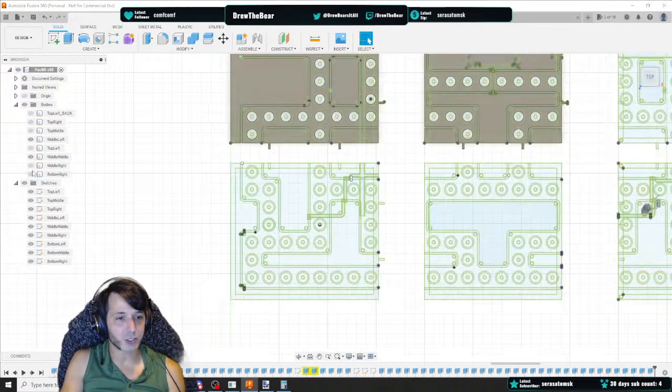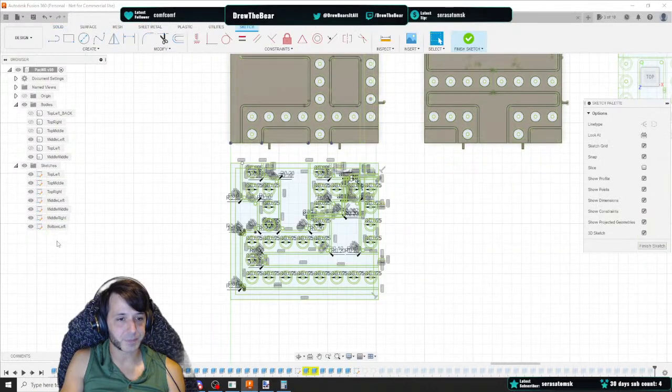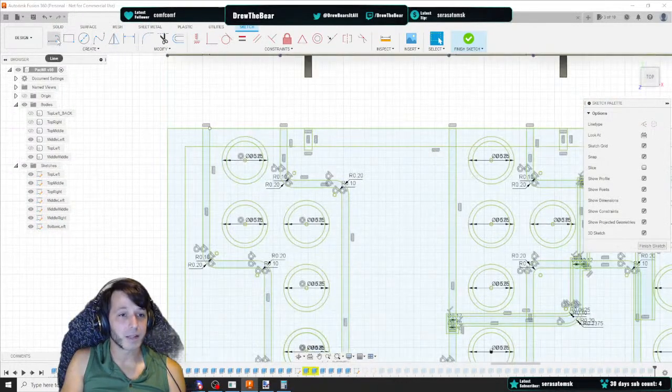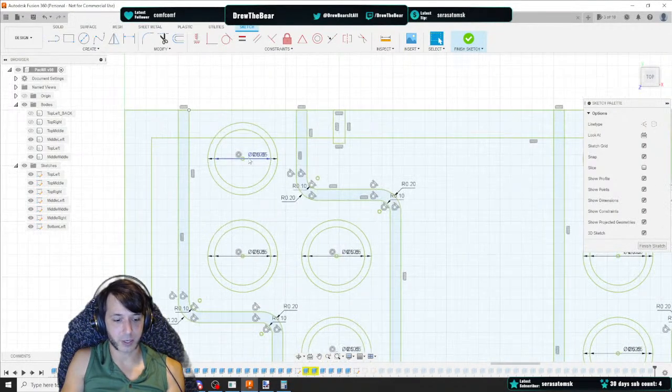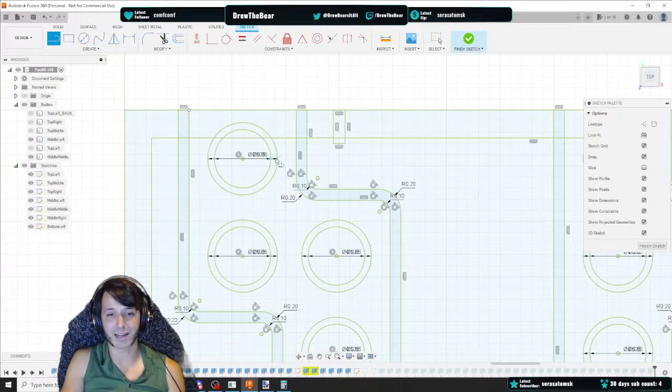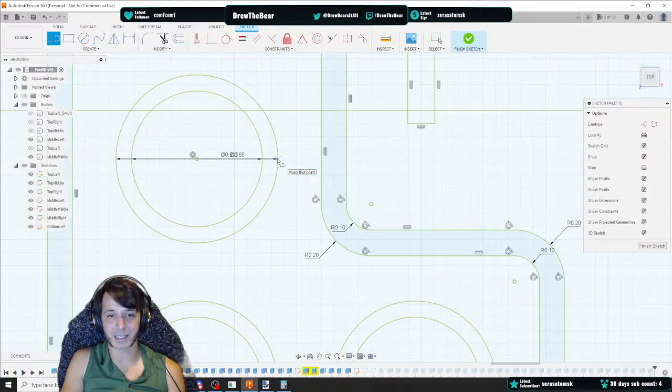So we're going to make the sketch. We're going to go bottom left. These are fortunately really easy to make. I just go here, I hit line, I walk it over without clicking, and it keeps me in line with the center, which is really nice. It locks me there. Go all the way to the edge here. This X represents the point on this axis, on the Y, where it matches the outside.